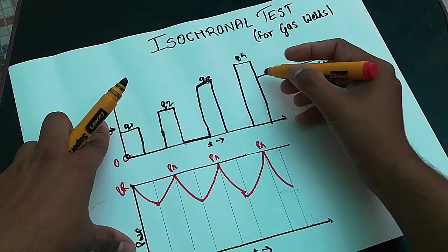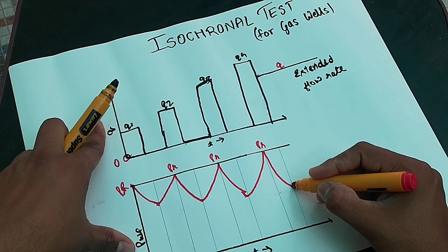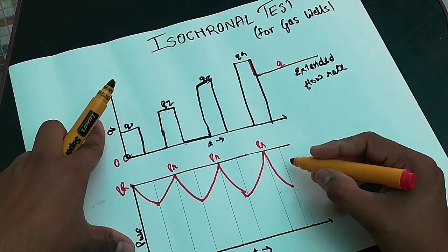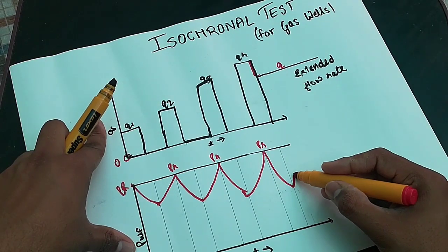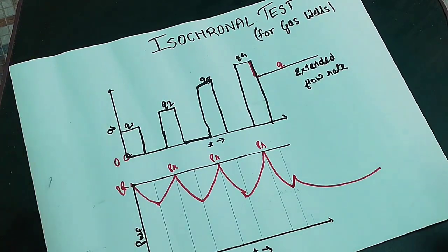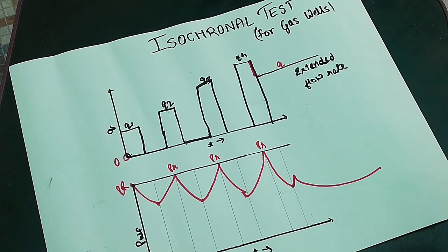So due to this we will flow at a constant flow rate after this Q, and due to this a small decrease in flow rate can be seen, due to which a small buildup would be occurring, and after that a constant drawdown will happen. We do the extended flow rate test because it shows how our gas well will behave in constant flow rate conditions. So now let's get back to the presentation and see what other observations could be deduced from this.